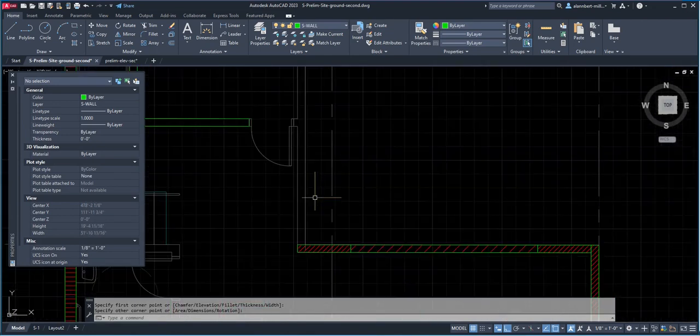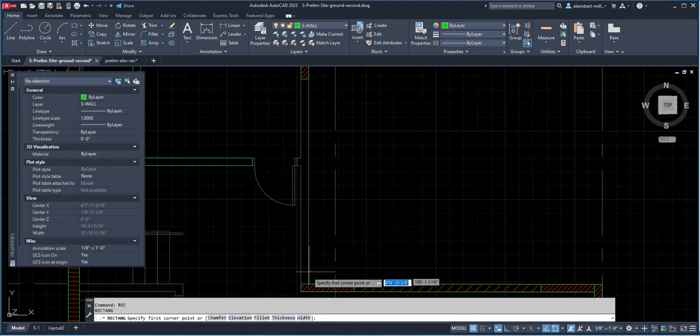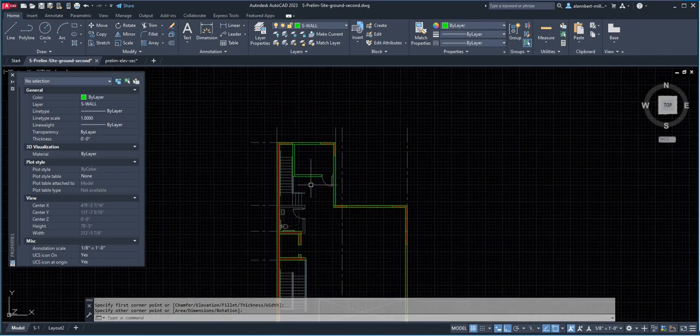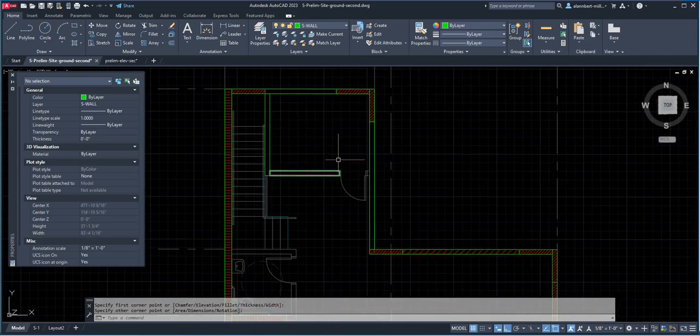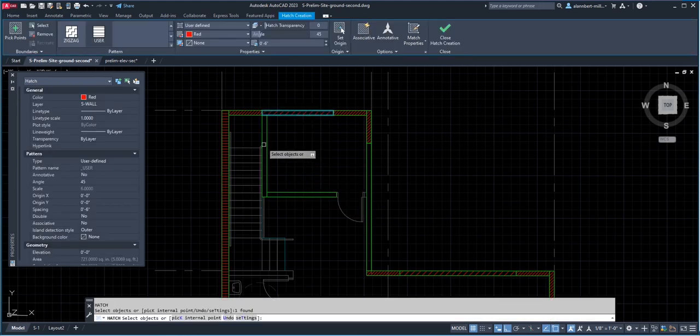Some engineers would not address the interior walls because they are not structural. They're just basically divisions, and the architect wants to divide this area, so he's putting in a wall. If it's not load bearing, it doesn't carry any weight. It's not part of the structural system. Then sometimes some engineers would not address that at all. It depends on the engineer how he needs to do his work.